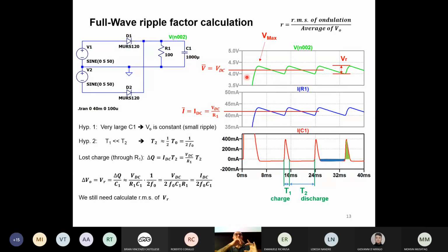Apart from the peak voltage, what is worse is that the 3 volts can be within the threshold band where you don't know if a digital input signal is 1 or 0. This means you can lose the information about the incoming bits because the voltage is going up and down too much. So probably you need a better filtration of the input voltage. This is just a simple example to understand why some equipments are more or less tolerant to the input ripple.